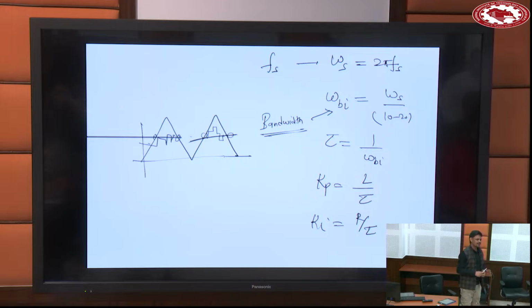Why is the synchronous machine not self-starting? The induction machine is self-starting, the synchronous is not. Why? The rotating field is also there. The point is you are asking the rotor to be Rajnikant, that I say go, and after 20 milliseconds the field is flipping from N to S, S to N. In 20 milliseconds, the rotor has some definite inertia. It cannot respond. That's why.